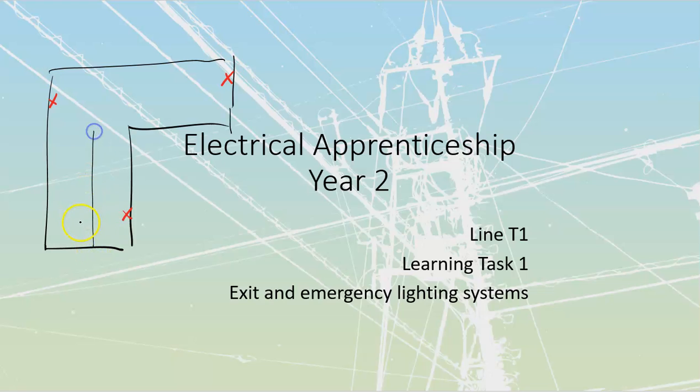And then what we're also going to have is a number of, and I'll just draw this in here as kind of a main corridor or something like that. We'll stick a doorway through to there. You're also going to have emergency lighting. Emergency lighting helps people find their way and get to the exits. It's going to be little lights, we'll draw them in here as little V's, that keep public accessible areas lit so that people can find their way to those exits. Two separate systems, but designed to work in conjunction with each other.